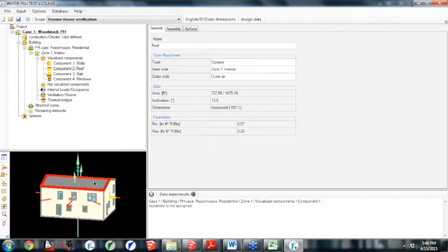These percentages represent the amount of area on each wall. The reason south and north aren't equal is because it already subtracts out the window area. So this area you see right here, 872 square feet, is for the north wall minus the windows. So the windows are already subtracted out. So if I were to click on this, let's see, this is the west wall, 680 square feet. That's subtracted the window. This is the total area of the walls here, 2942. Inclination is 90. We know that. Okay, so now I'm going to go into assigning the assemblies.